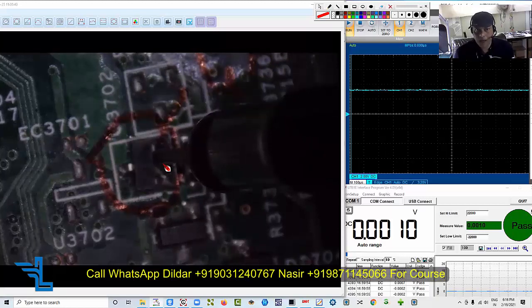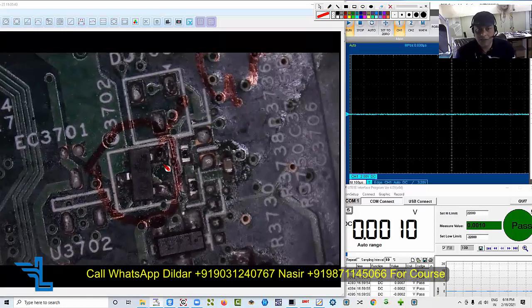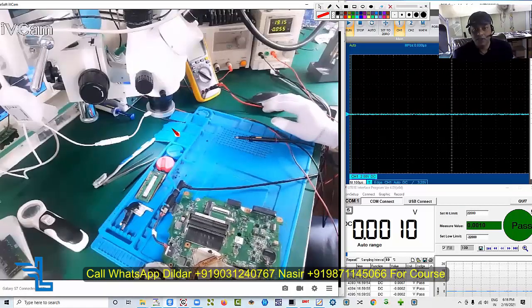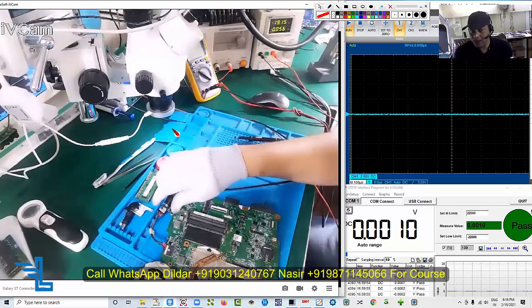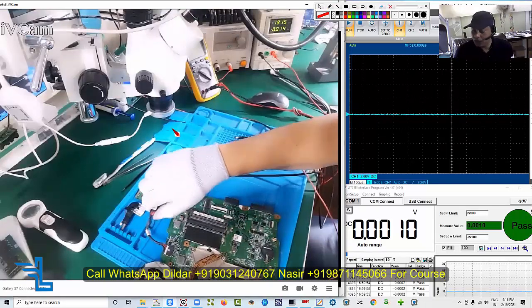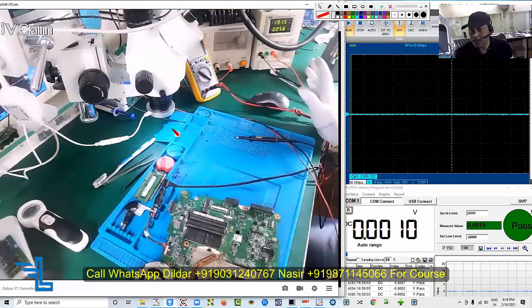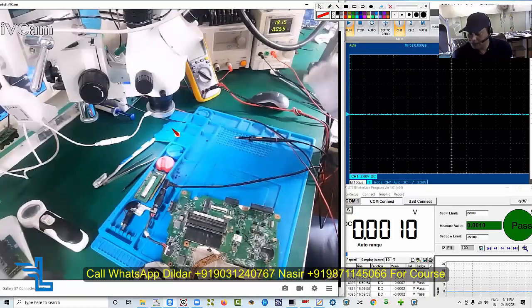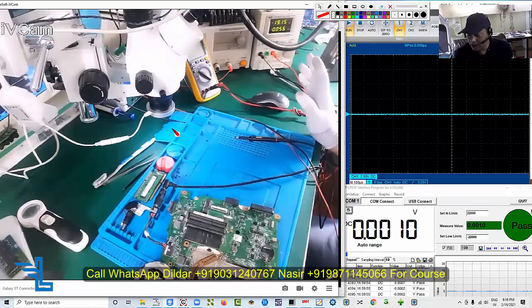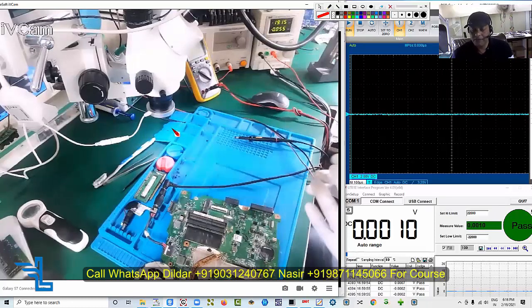As far as the load is concerned, you can see the load, that as soon as I inject the DC jack into the motherboard, you see 0.56. I think it is a little bit more than required, because in the always concept, if the board is not in suspend mode, it is having the always voltage, S5 voltage, then it must consume 0.35, not more than that. If it is having more than that, might be somewhere in the motherboard is shorting.